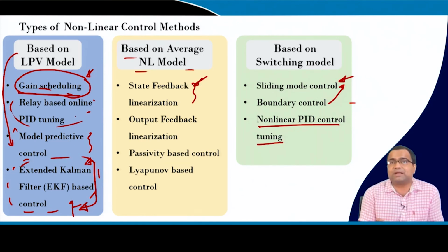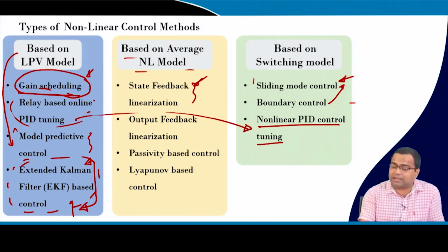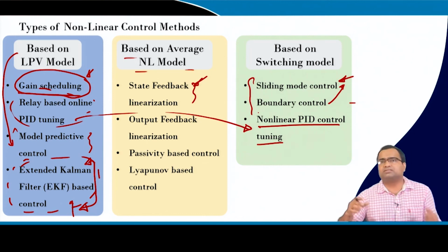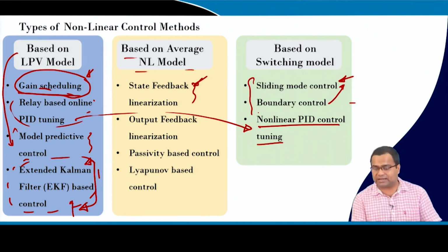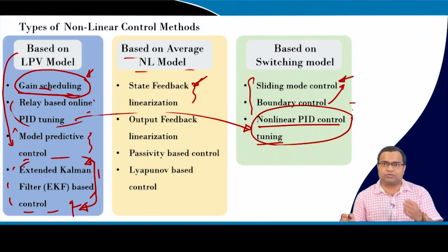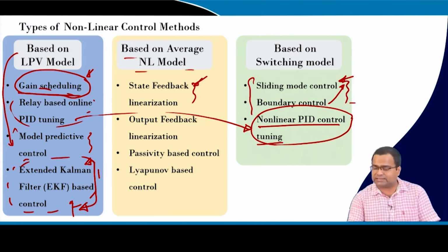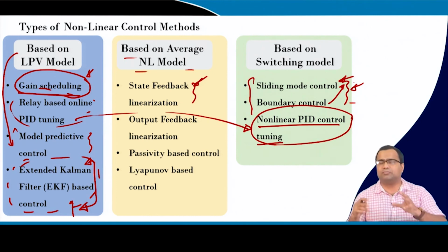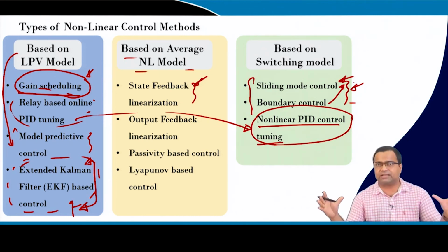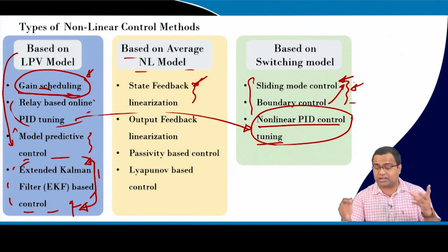You can still use PID control, but we can incorporate the ripple parameter to get the performance which can be achieved by a very fast, sophisticated nonlinear control. But here we can simply use the same PWM controller, because all these techniques require maybe variable frequency operation or something like that, and the structure, the surface of the controller, can be higher order.